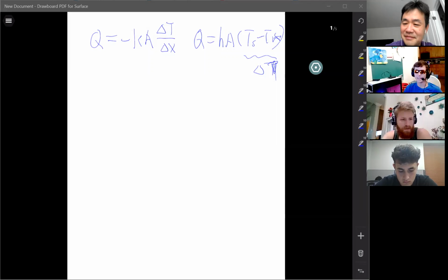I guess it depends. If you look at it, it's convection. But if there's no difference between the outside and the surface temperature, that's zero. So zero times whatever your H is, it doesn't make a difference. Yeah, believe in math. You're an engineer. Don't believe your intuition or whatever guess you feel is more reasonable, but believe the equations the previous engineers developed for you.